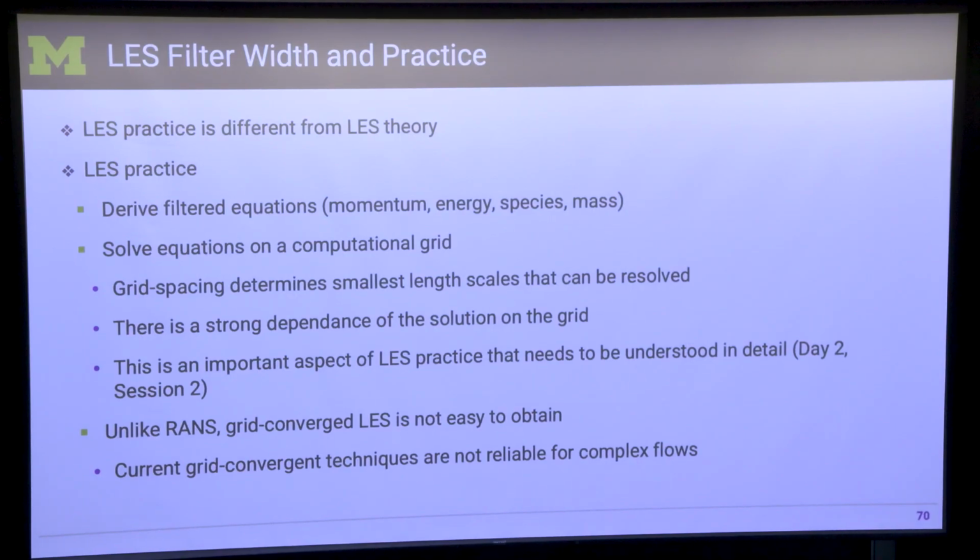So we are going to use LES, and for LES we need to do filtering, and if you do filtering, you have to do modeling. But the promise of LES is that even though combustion happens at the small scales, we are somehow able to overcome that limitation. And as a result, we are able to do things much faster, right? So you're able to simulate the whole geometry.